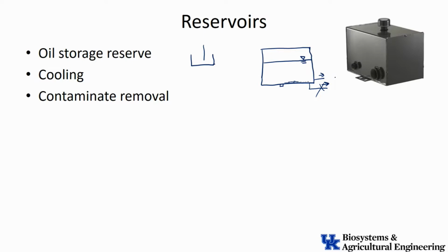Now the other thing I think about is where do I bring it when it comes back? So it goes out through the system and it comes back. Where do I bring it? Well, a lot of people say, hey, let's just dump it in right there. Okay, so we bring it in the top, we dump it in, and that's great. But it's not great because think about what happens. I got a lot of fluid that's coming back through here. It's hot fluid. And I dump it in, it's going to spray, it's going to hit down here, it's going to splash, and what's it going to do? It's going to create little air bubbles in here when it splashes.